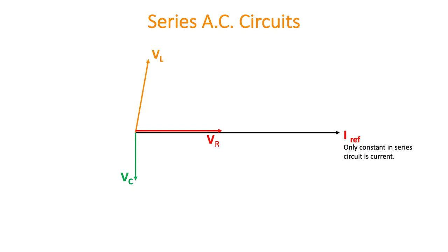But of course, no phasor diagram is complete until we've added them up. So let's add them up. This one nice and easy first. So we're simply adding VC to VR, do a parallelogram, close the hypotenuse of the parallelogram, and there is volts R plus volts C.